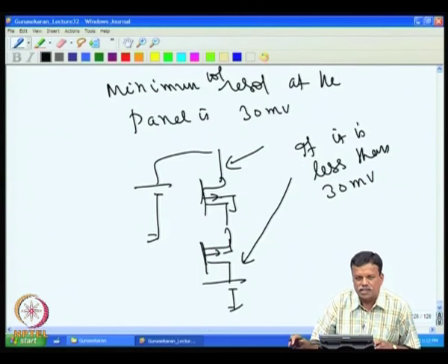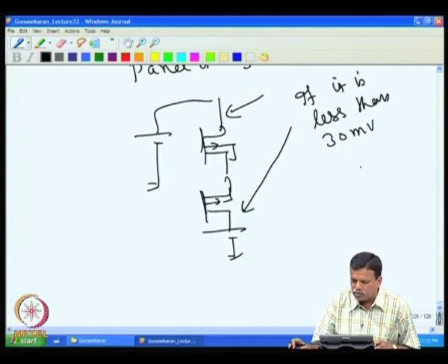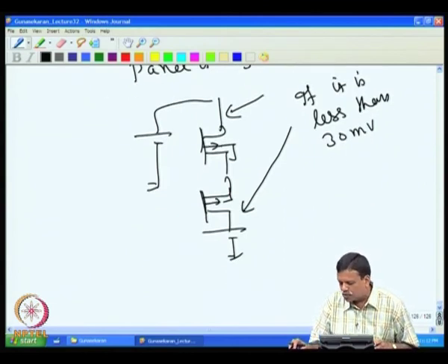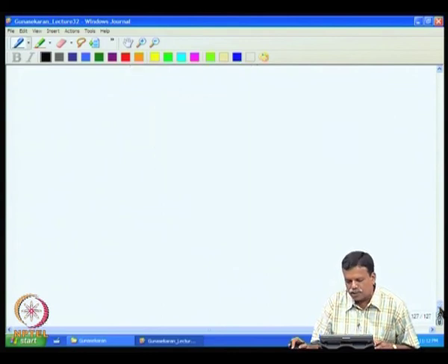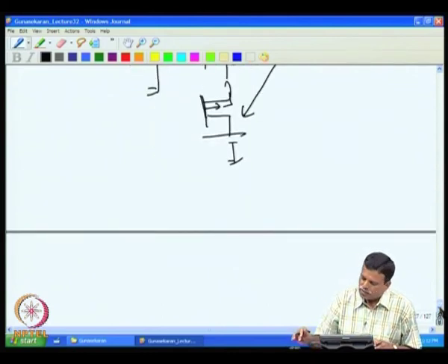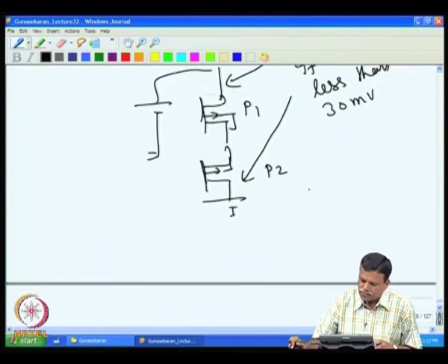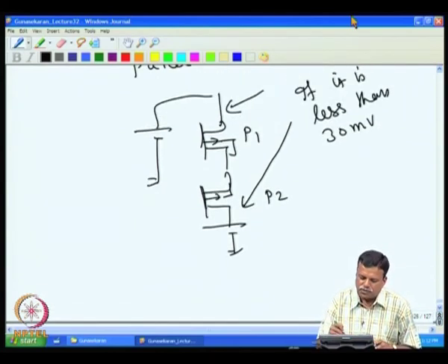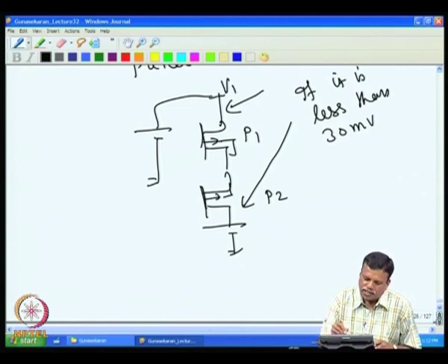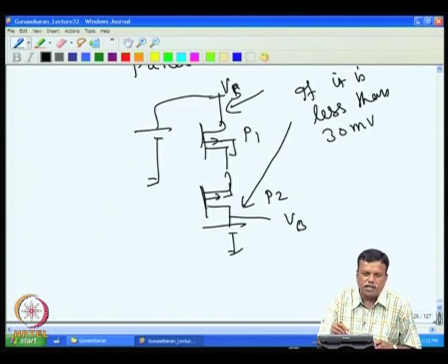So, to avoid this complication, what normally they do is that they will switch off the P1 and P2. So, in actual case they switch off the P1 and P2 for a fraction of a second, then measure the V panel and then V solar and then V battery, because when it is off, the voltage will be correctly known.